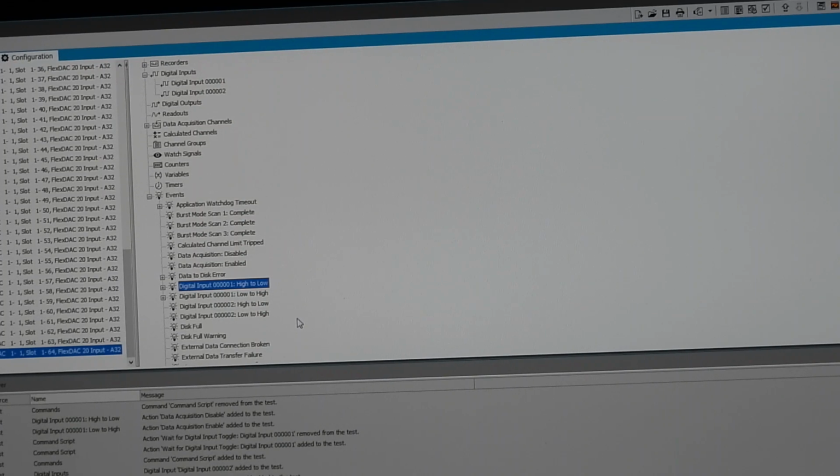I'm assuming it's running at higher than system rate, and you're not going to see anything because it's going to be less than 1 over 6144. But if there is some impact to that system rate, if it's 256 that you're running at, there may be up to 1 over 256 of a clock tick that could potentially be missed in between the turn on, if it's only sampling at that rate.